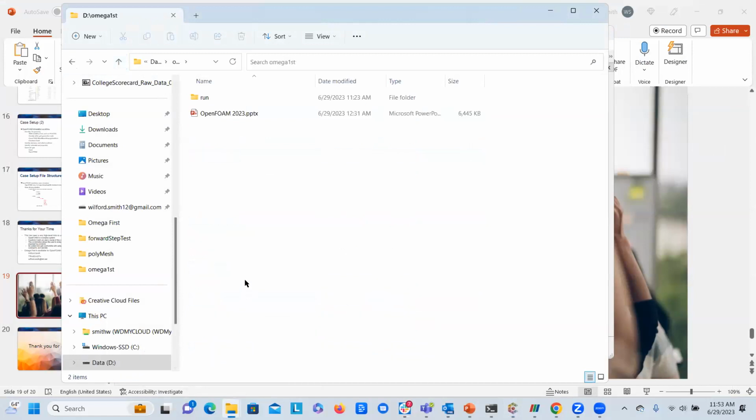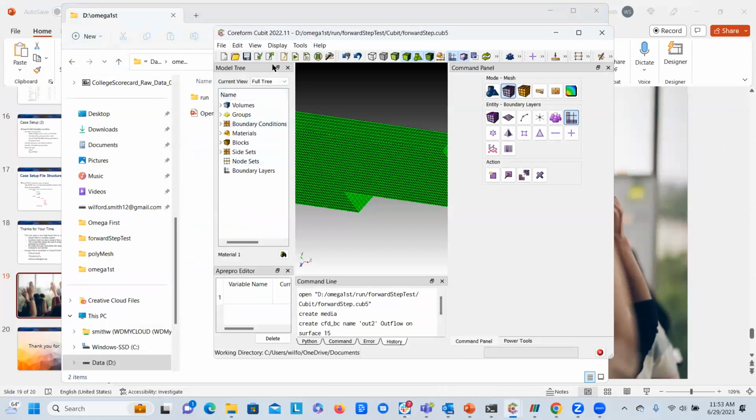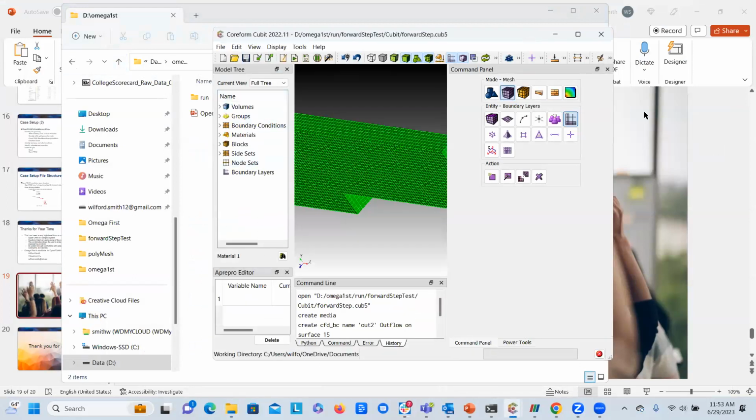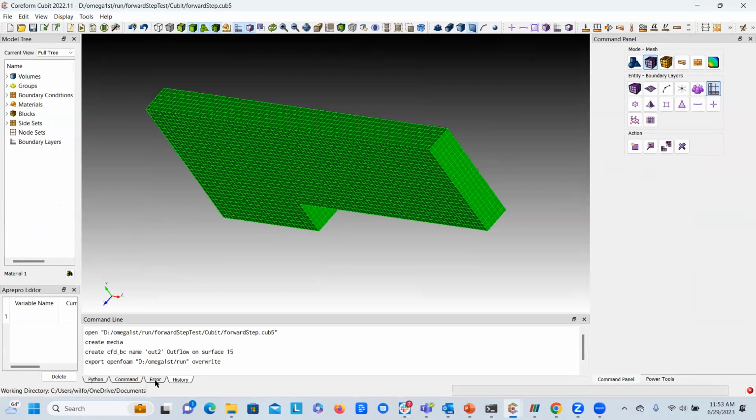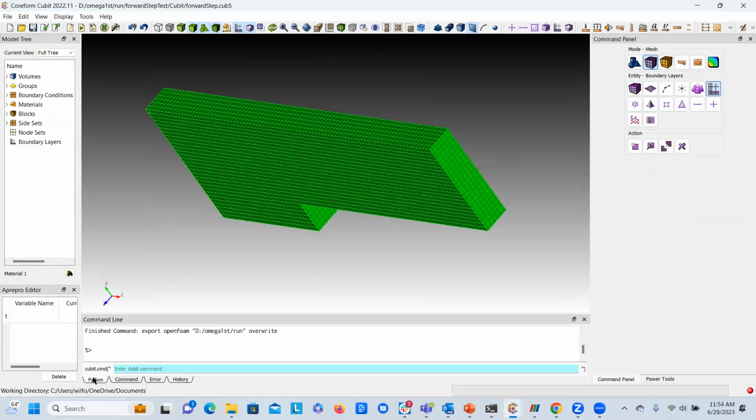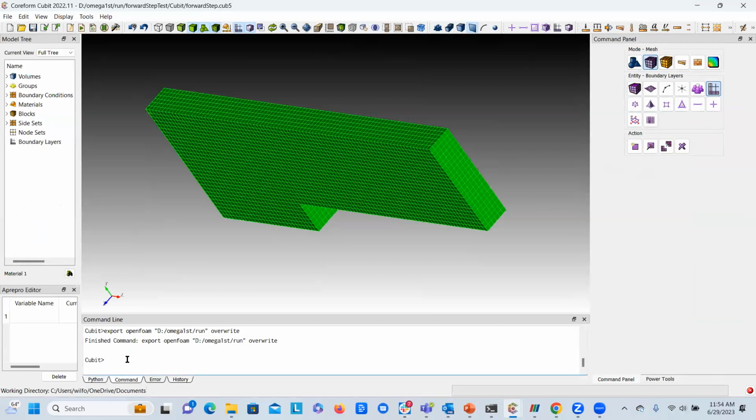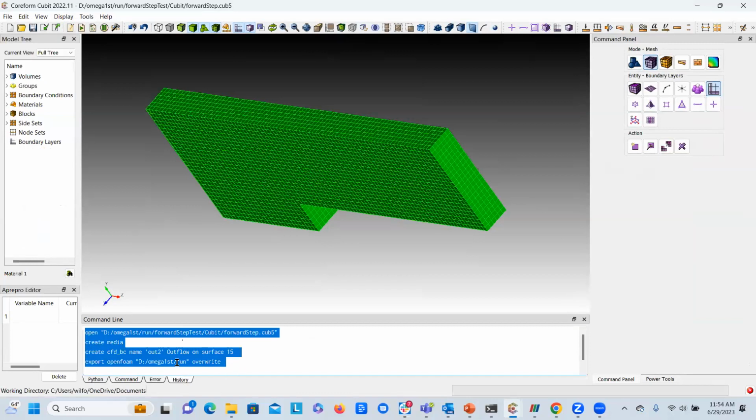And I don't. Well, when I set this problem up, I usually would capture my history. So, for example, within OpenFoam or within Cubit, down at the very bottom, you see that they have the Python. I can input the Python. I can input regular command structure in the errors, but there's this history that shows me all the things that I've done within the editor or within Python or within Cubit over the course of the simulation, the generation.